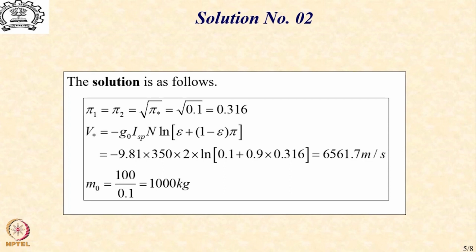And you will find that the optimization techniques that we talk about essentially aim to look at slightly better structure, slightly better propulsion, in order for us to have significantly better gains in terms of the launch cost, which is typically expressed in terms of the payload fraction, which is so many kgs of payload per kg of lift-off mass.